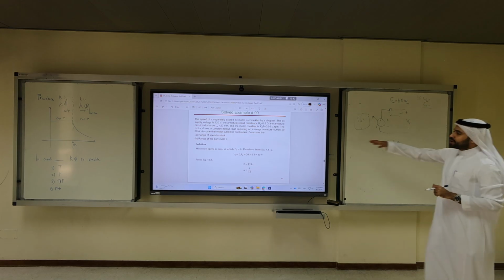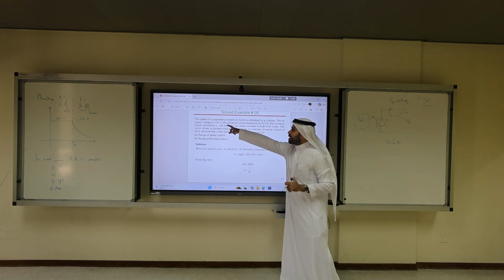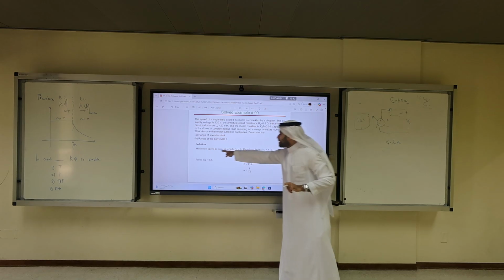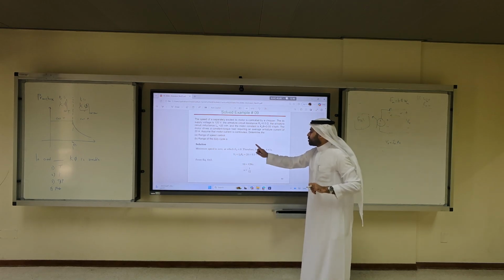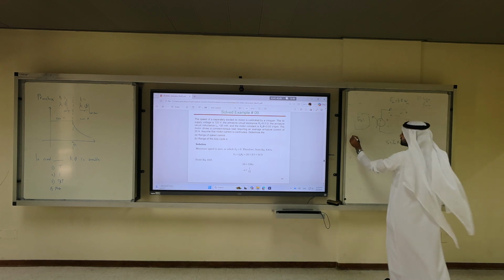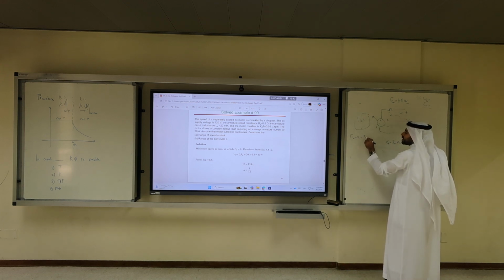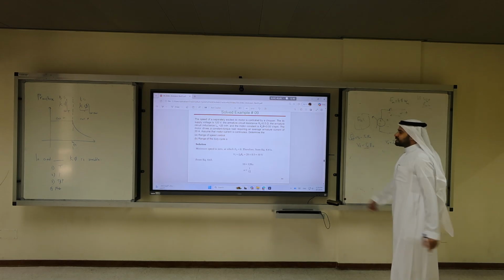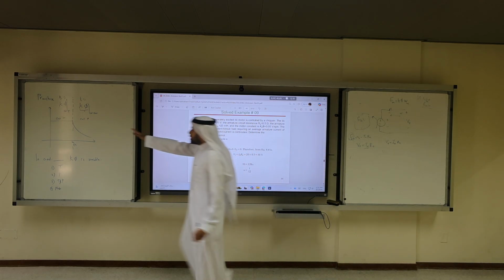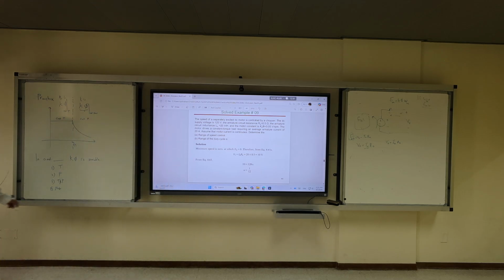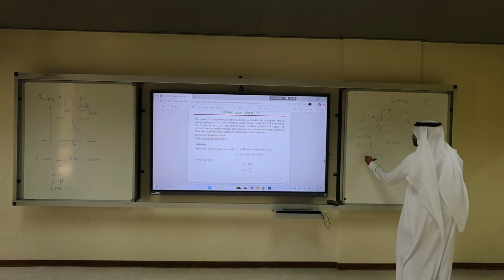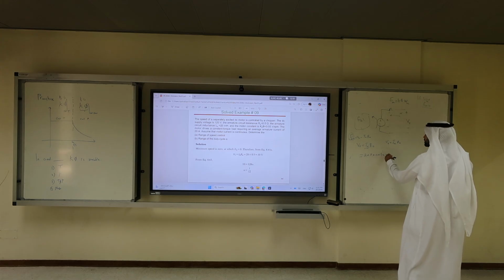So what is VT? He didn't tell you even the supply. No, he told you the supply, it's 120 volt. So the question is, for omega speed 0, we have EA is 0. From this equation, EA equals VT minus IA RA, because EA is 0, VT has to equal IA RA. But IA is fixed in the question. Across this region, IA always has an average value of 20 amps. So this means VT would equal 20 times 0.5, which is 10 volts.